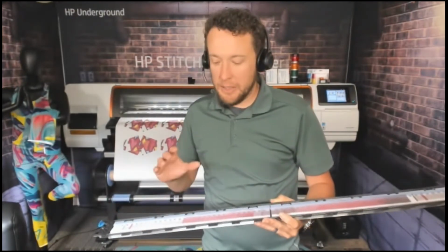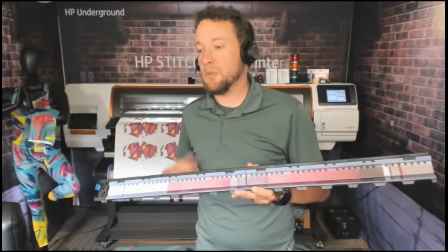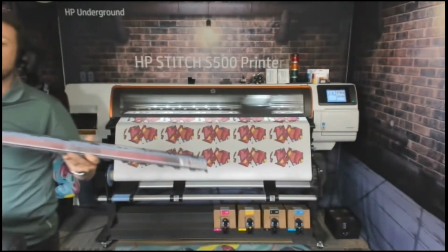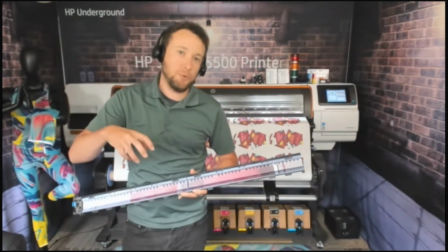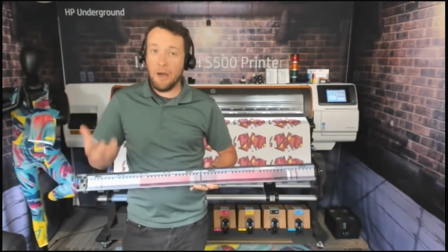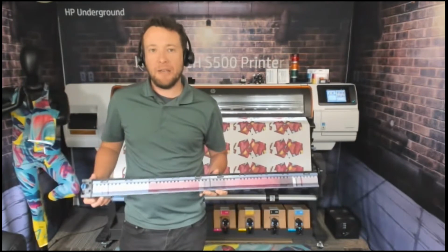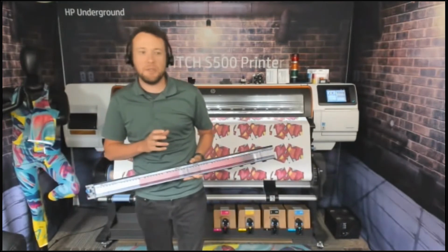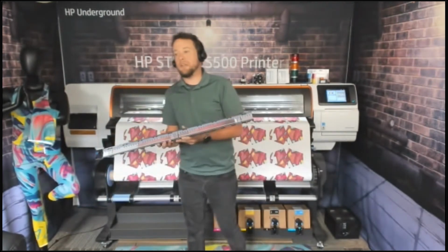And this ink collector, there's actually two of them that sit in the print zone. You take the platen out, you put this in its place, and the machine knows that you installed the ink collector as well. So this gives us very good opportunity to do direct to fabric. So flags, what do you want when you print flags? You want a good punch or a good pass through to the other side. On some of the flag materials that are out in the market, we can get up to about 90% pass through. Again, that depends on the fabric or the material that you're using and the coatings that are on that material. We'll talk about that next week in our applications deep dive.